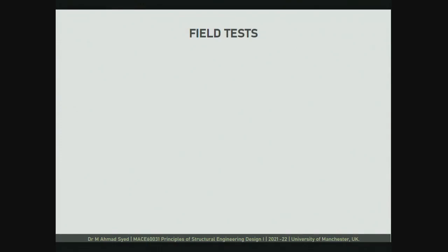Okay, so we have in situ tests. Now, in situ tests are further subcategorized into two types of tests. One is surface test, the other is a borehole test. In surface test, obviously, whatever test we are doing at the ground surface, by doing something, we are extracting valuable information. I'll cover that in a minute. What is that something? In a borehole test, obviously, we create a borehole in the ground and do some testing within the borehole to extract valuable information.